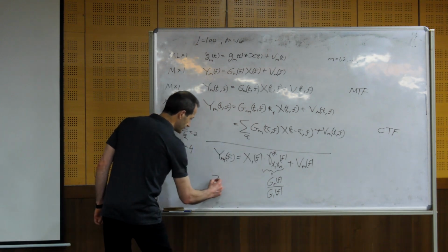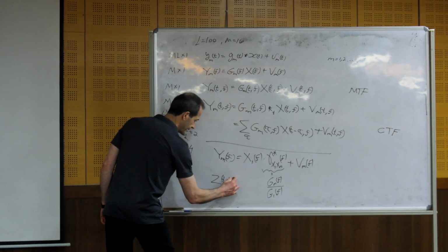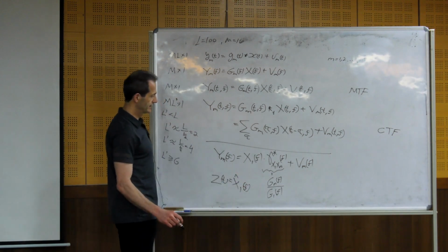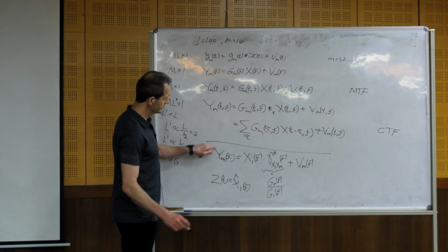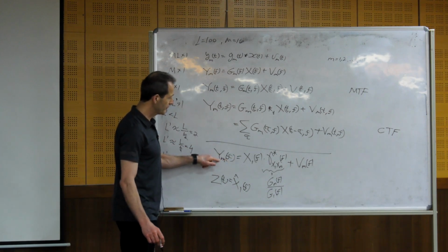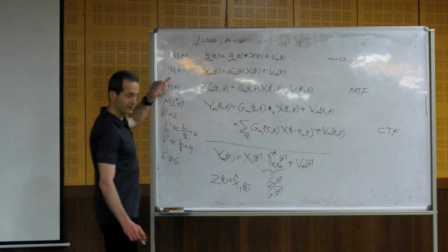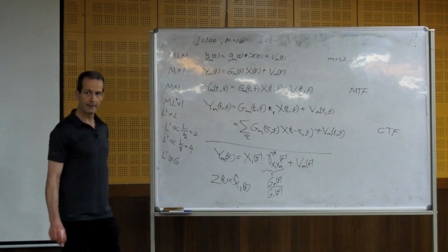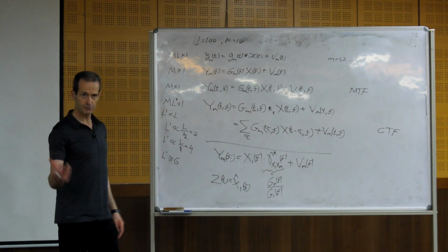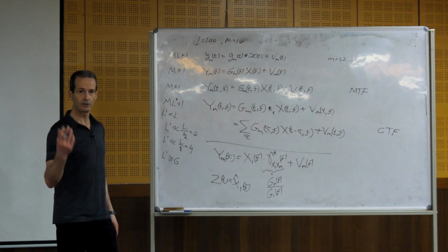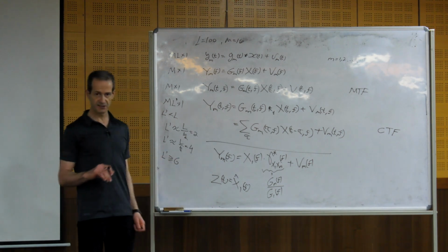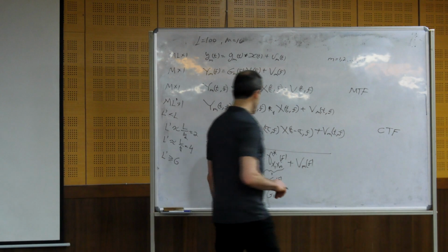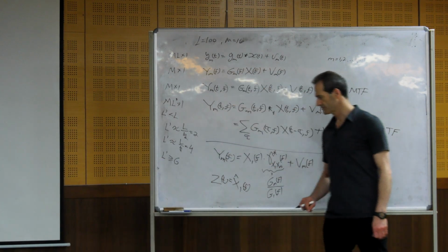So we can obtain an estimate of the desired signal for frequency f in the reference sensor, using this vector of measurements, a vector of length m. So we can find a filter of length m that we apply to the m measurements for frequency f, obtained from the m sensors, and we get an estimate of the desired signal.